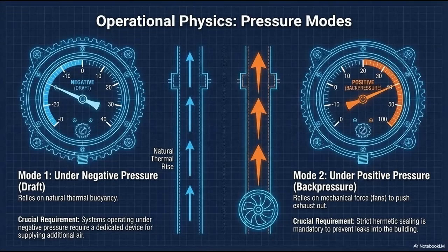No, not at all. It's a highly corrosive cocktail. The exhaust contains sulfur and nitrogen compounds from the gas. Exactly. So when that water vapor condenses on the freezing brick, it mixes with those compounds and creates sulfuric and nitric acid. The chimney is quite literally sweating a weak acid. Sweating acid, that's exactly what's happening. And because brick and mortar are highly porous materials, they absorb this acidic sweat like a sponge. It is a devastating chemical attack from the inside out.